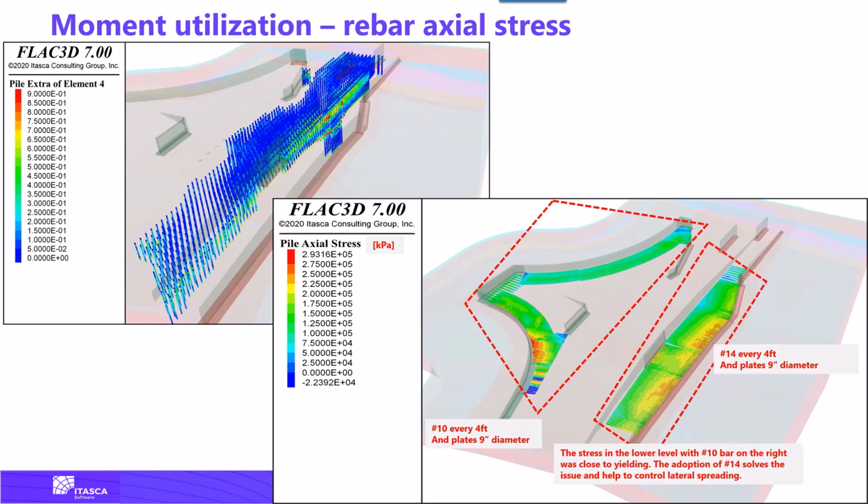We have a few spots in which we are going up to 0.9, and there are a few regions in which we also had a little bit of reinforcement at the top. But without the horizontal rebar that we see in terms of stresses mobilized in the lower portion of the picture, the situation would have been not compatible. Even adding full reinforcement or heavy cages, those vertical columns would have been suffering a lot.